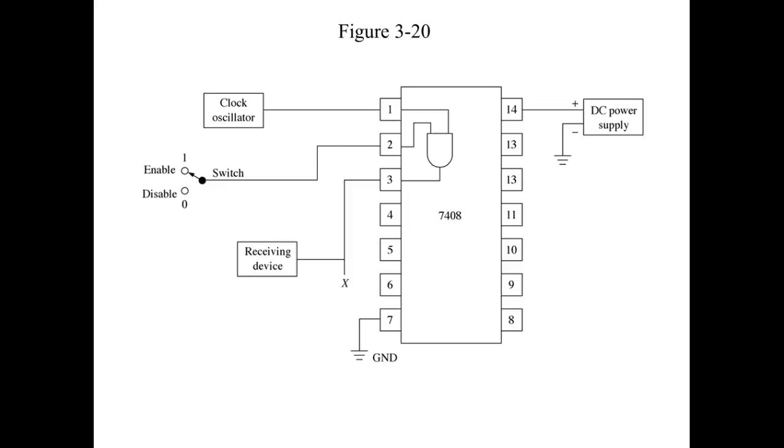So this is how it would be wired up, but what you got to understand, this is kind of misleading, and somebody in this class usually does it, is they'll need 4 inverters, and they'll say, Rich, I've only got 2 inverters in my kit. But what they're doing is they're looking at it as a chip and not as 6 inverters inside one package. So we have a lot of people that needed to wire this, and then somewhere else they needed this right here, and they say, well, I've only got 1 of these chips, but they forget there's what? There's 4 of them in there. And the only thing they have in common is they share the same package and they share the same power.